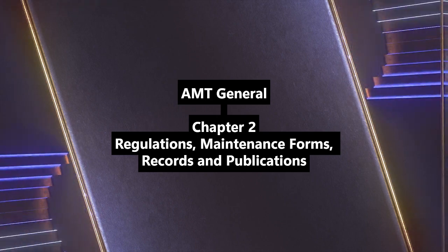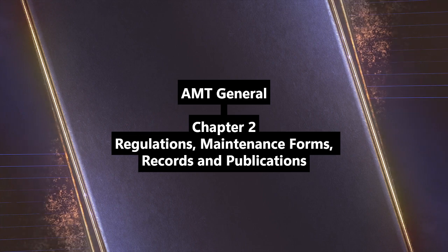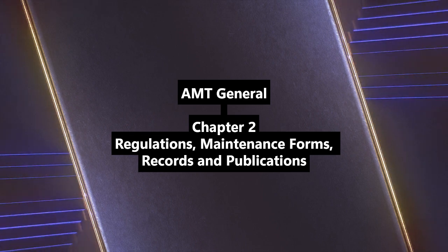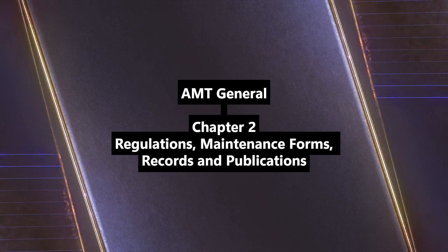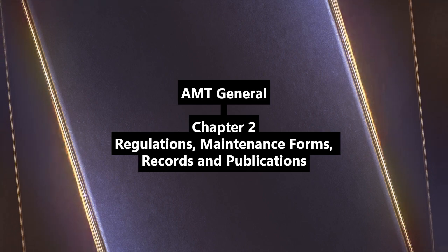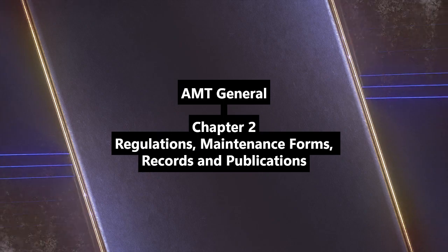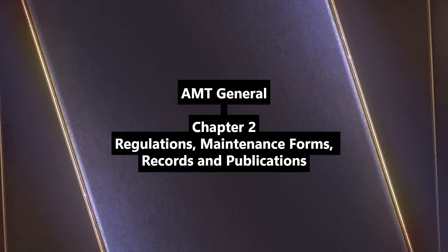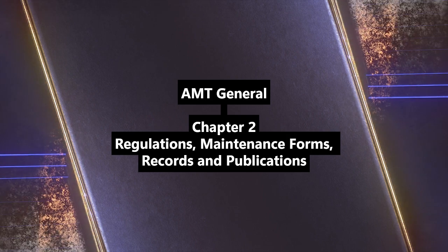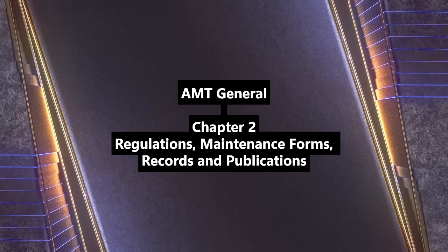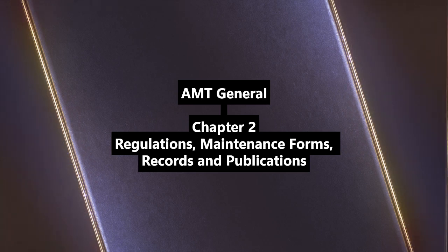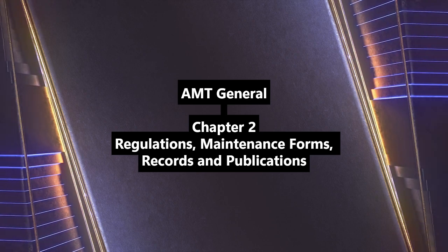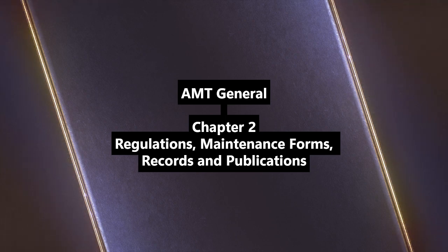Okay, that covers Part 43 in detail. Now let's look at 14 CFR Part 91, General Operating and Flight Rules, focusing on the maintenance aspects in Subpart E. Right. While Part 91 is mostly about flying the plane, Subpart A sets the stage. Section 91.7(a) says you can't operate an aircraft unless it's in an airworthy condition. Back to that core definition: conforms to type design and safe to operate. Exactly. A pilot's pre-flight check mostly covers the safe operation part. Determining conformity often means checking the maintenance records. So mechanics play a key role in helping owners meet that responsibility.